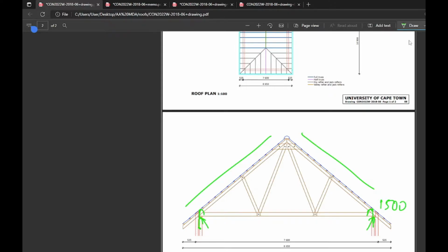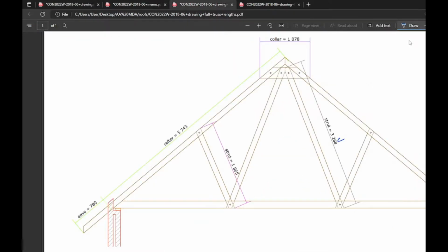One end fixed to brickwork, one end fixed to timber. Basically, I stand under correction, but whilst it's enough weight to hold itself down, negative pressure from winds does create some sort of lift that wants to pull the roof right off the wall. So obviously you do need to fix it down to your structure, okay? I don't know the details, you're going to have to figure it out yourself or ask a lecturer. So that's that.